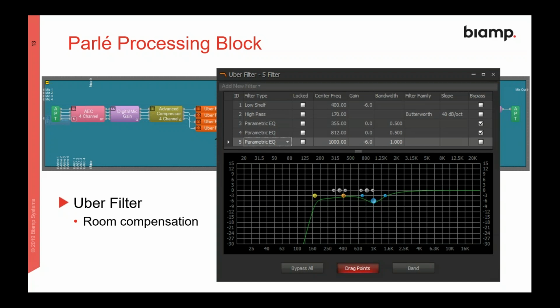A microphone typically gets less directional as you go down in frequency. Most microphones, a cardioid, a super and hypercardioid microphone, are almost omnidirectional below 200 hertz, definitely below 100 hertz. So they pick up a lot more noise, and then the higher frequencies are nice and directional and pick up only in the direction that it's pointed.